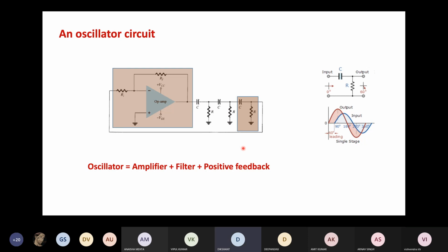So can we choose the non-inverting part of the op amp, and then adjust the phase difference of this RC circuit? Yes, exactly, that's always the case. We can do that, but ultimately we need 360 degrees of phase difference, so we would need to use as many circuits as would produce a 360-degree phase difference, and in that case, we can apply this output to the non-inverting terminal.